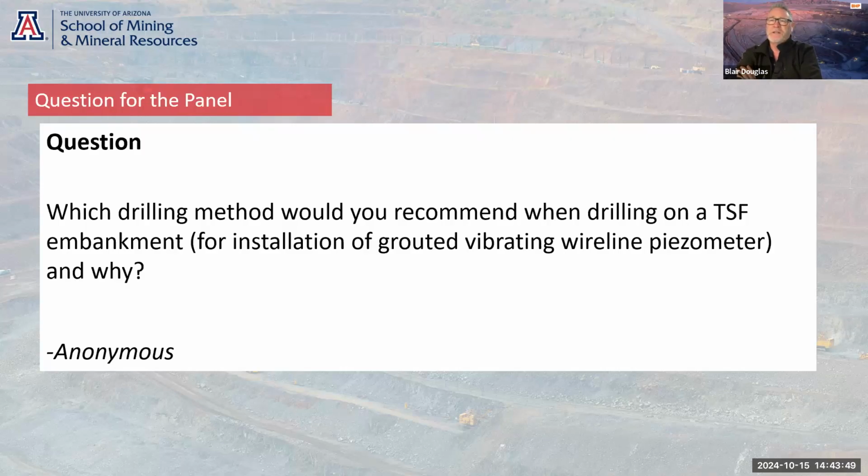Therefore, I think the drilling method needs to recover sample. You need to make sure you can correlate where you want to land your vibrating wire with the condition that you're looking for. Because if you are looking for some moisture zone down there, you really need to find a drilling method that allows you to look at that and couple it with geophysics.